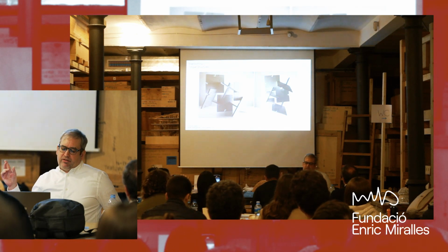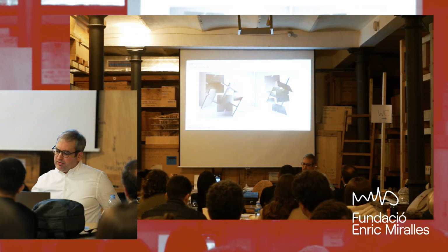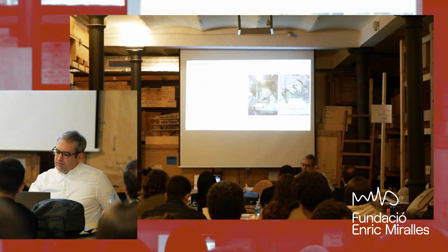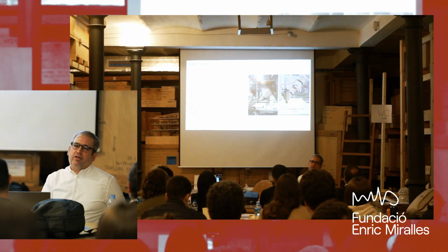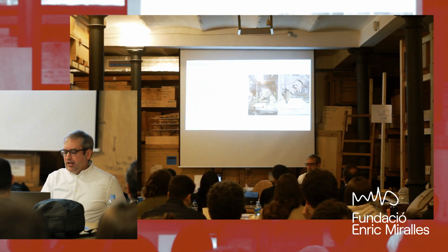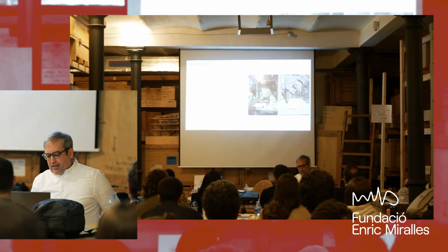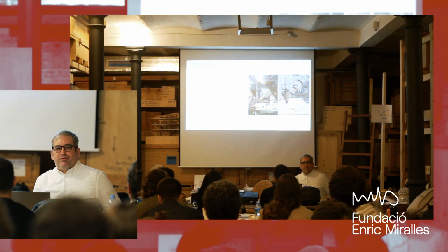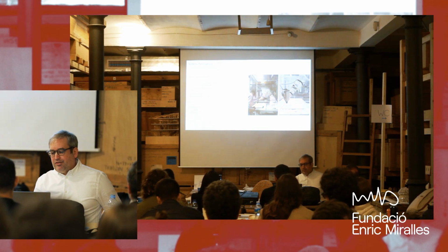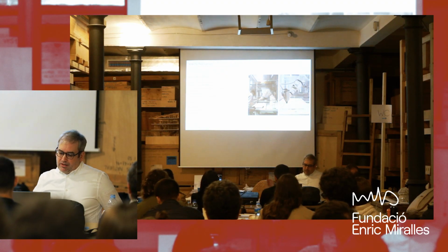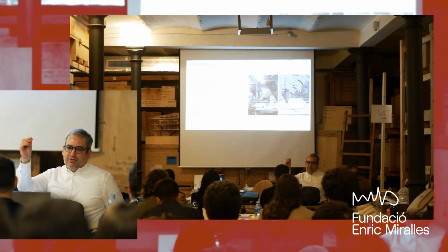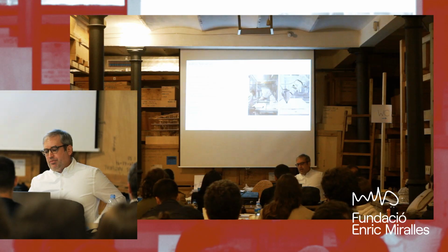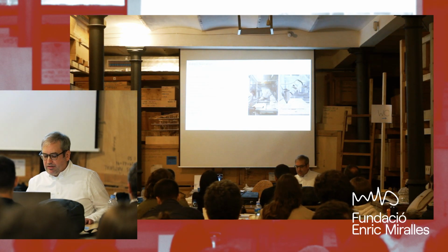Each of these elements is approximately 30 by 30 centimeters. And the reason for that is also some of the limitations of the production facility, which was this robotic arm that you can see here. And one thing that is always important when you use robots is safety. So we needed to make a kind of plexiglass cave around it, so that if the milling bit breaks, it's not becoming a projectile and hurting anybody. And because of that, the production space was a bit limited.